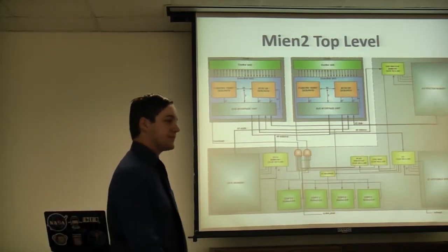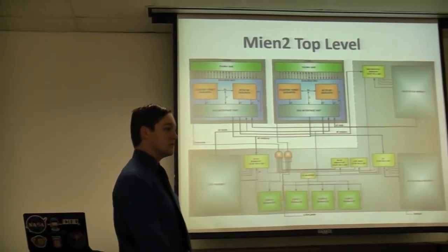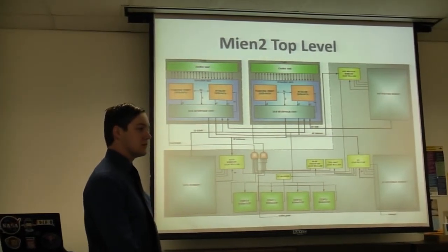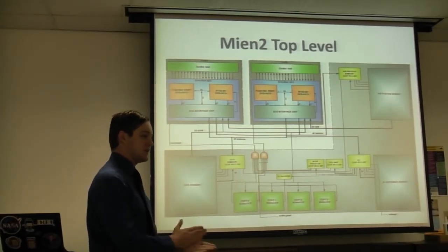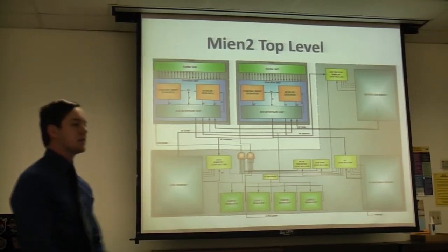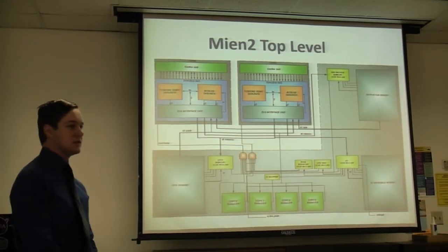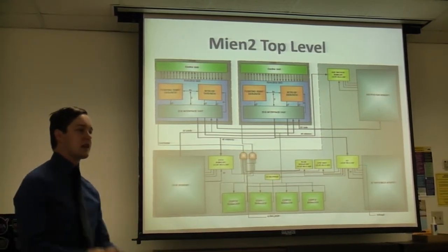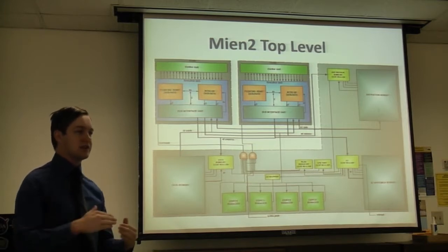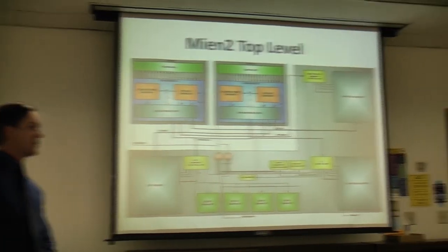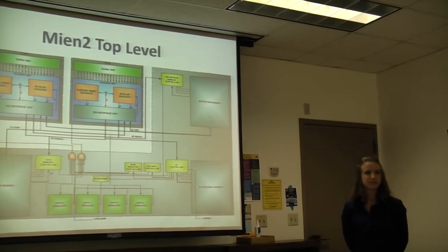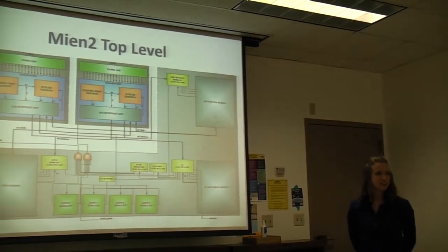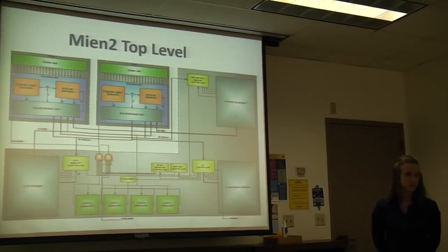Yes? So are the separate cores fetching at the same time or separately at different clocks? They are fetching 1 clock offset. They are asynchronous to each other. That's part of what the core wait is for, to synchronize the cores and begin execution again. So is it synchronous to core 0, and all the other cores don't match up to it?